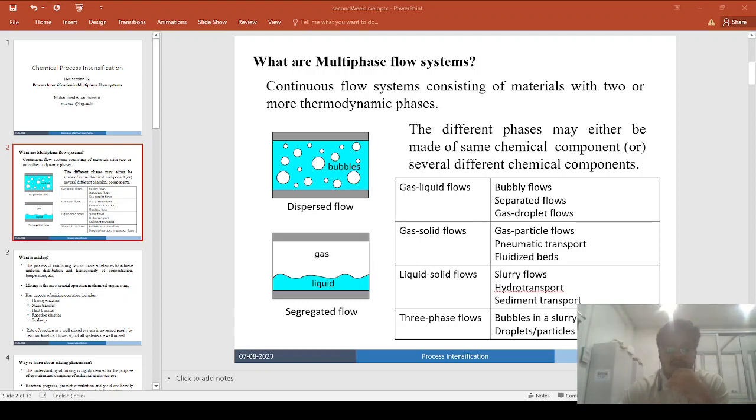Now as for the membrane distillation, the transport mechanisms are Knudsen diffusion, Poiseuille flow and molecular diffusion. The thermal boundary layer is considered to be the mass transfer limiting factor. So that is for the membrane distillation.